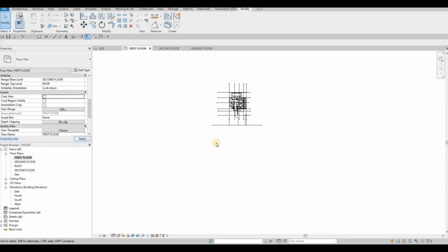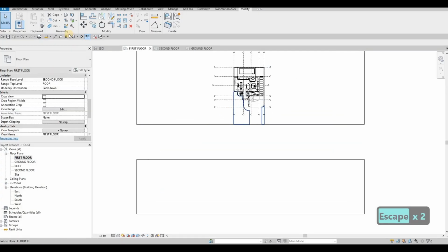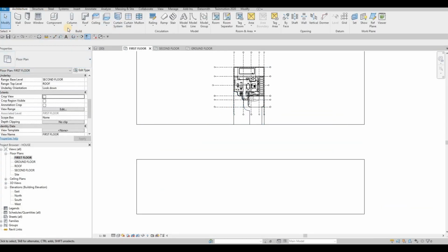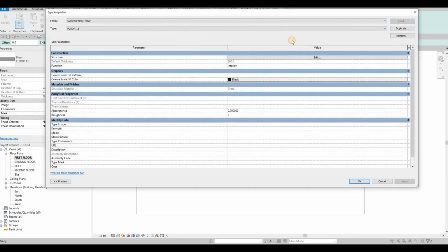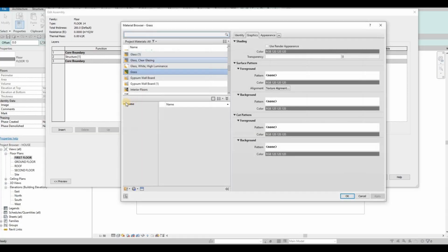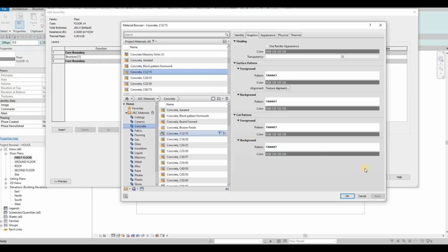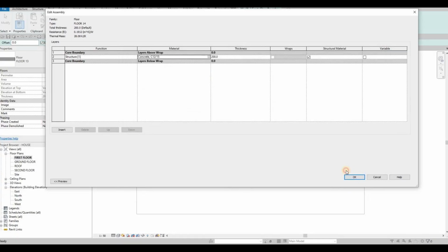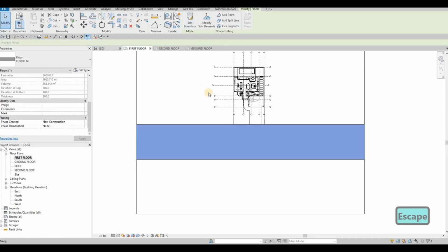And then here, crop view, uncheck that so that it's appearing. I'm going to then create another floor for the street. So duplicate this, 14. This will be another concrete. So I'm just going to put another concrete material randomly. There we go. Click finish.